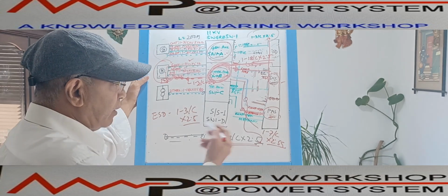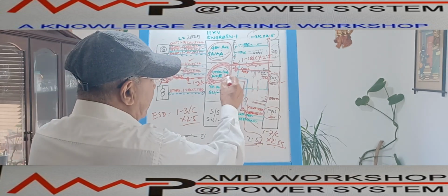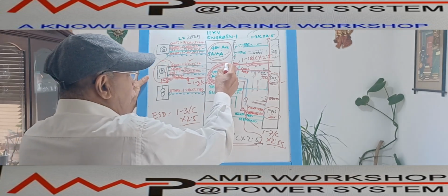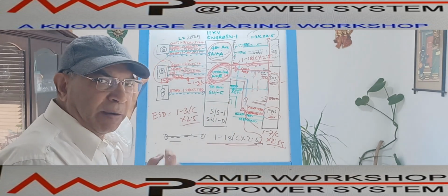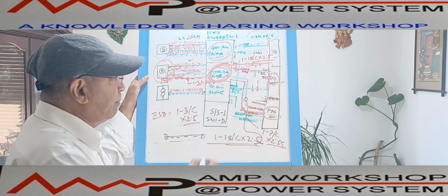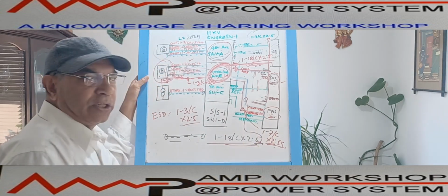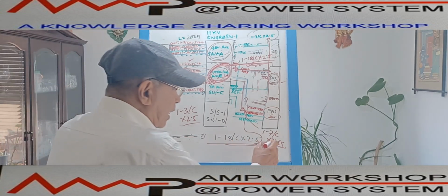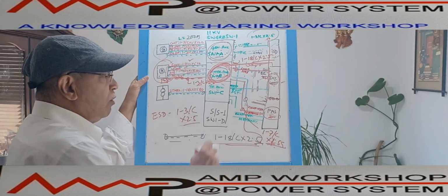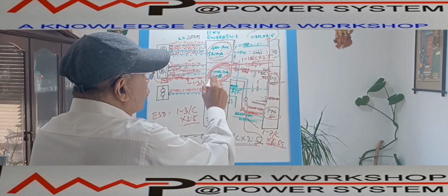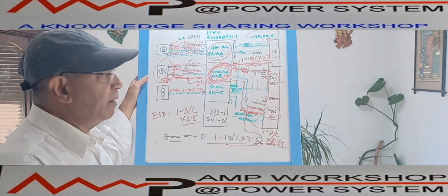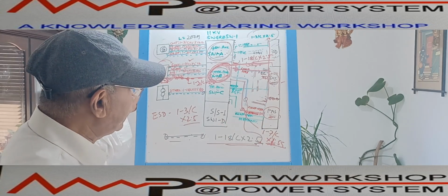It is a small, minor signal. It is a milliampere signal carried through the transducer. Actually the original CTPT supply is coming to a transducer, and this transducer gives the required output to monitor this. So the cable current is not very high, even 1.5 square millimeter cable we can lay to monitor these various electrical parameters in the PMS. So this is the cable.